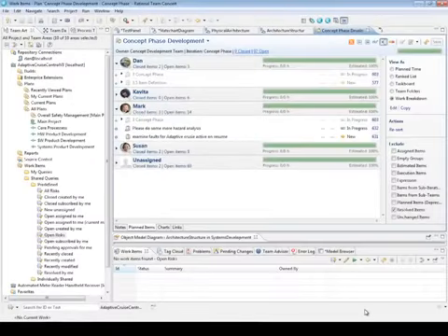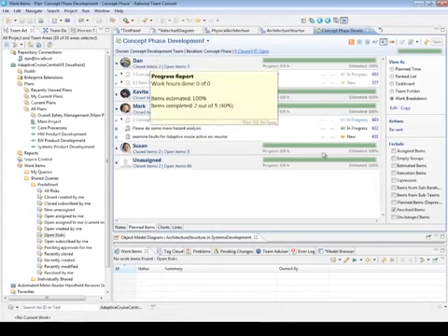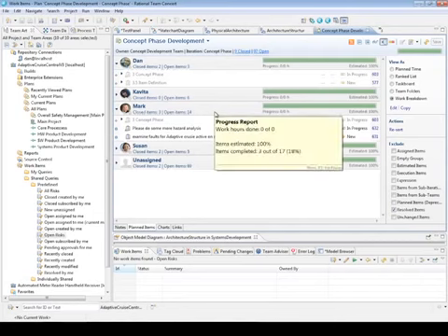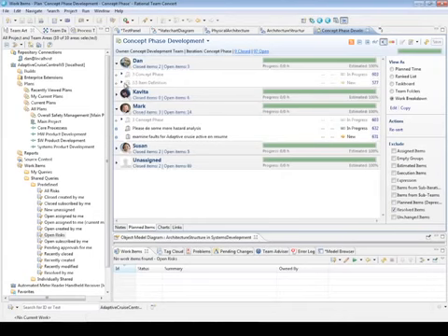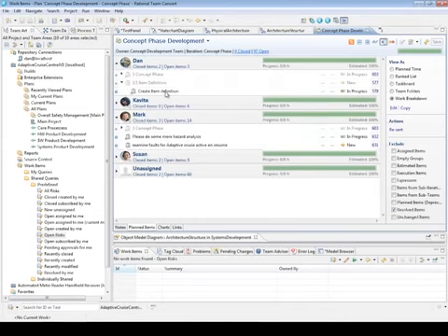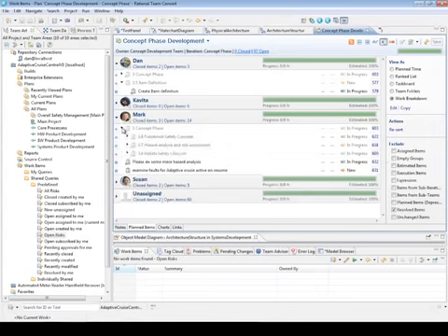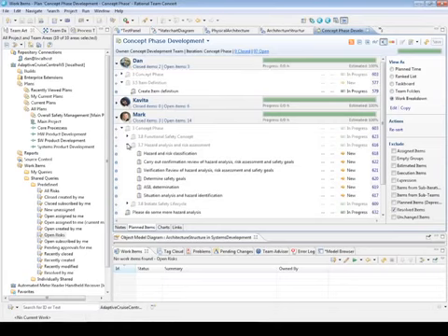Before we get down to Rhapsody, we need to understand the roles and the tasks that the main people will be carrying out in this particular phase of the development process. The two people that we're interested in are Dan, who is the developer, and Mark, who is the safety analysis engineer. Dan has to create the item definition, and Mark, as part of the hazard analysis and risk assessment, has to do things like the hazard and risk classification, determine safety goals and the ASIL determination. And these will all be captured in Rhapsody.